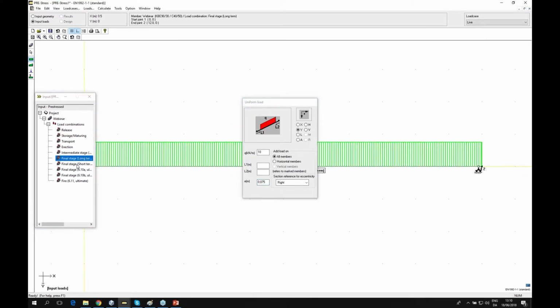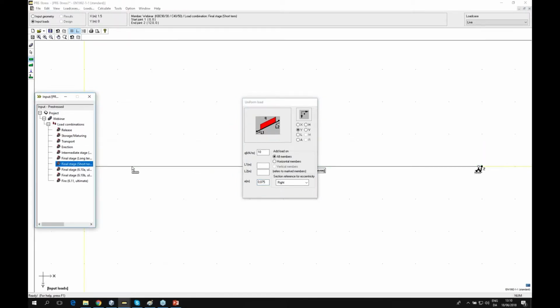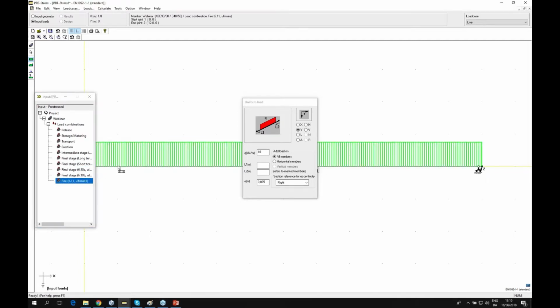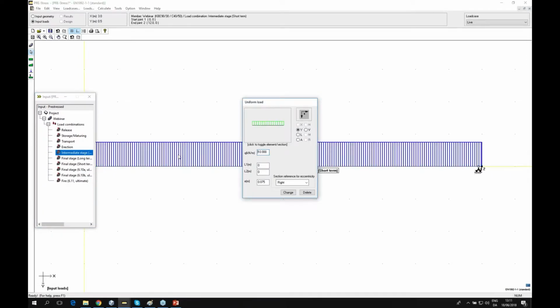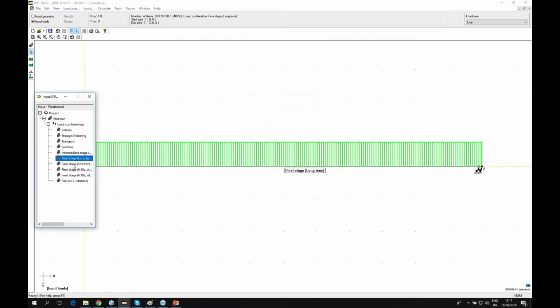And I will actually go to that section and see what I mean by the right edge. Once I've placed my loads, I can see here my cross section, and I have the right edge, which is here, and I have the eccentricity of 75 millimeters from that right edge, as I can see the arrow pointing. So I have it somewhere around here. So I'm okay with that for now.